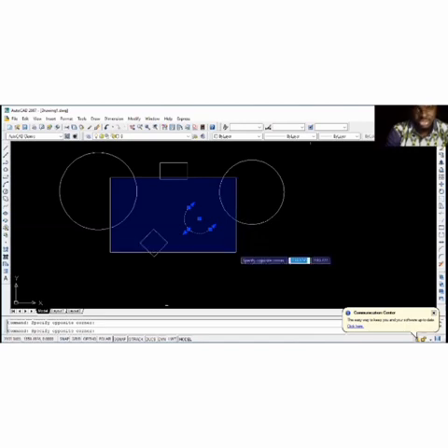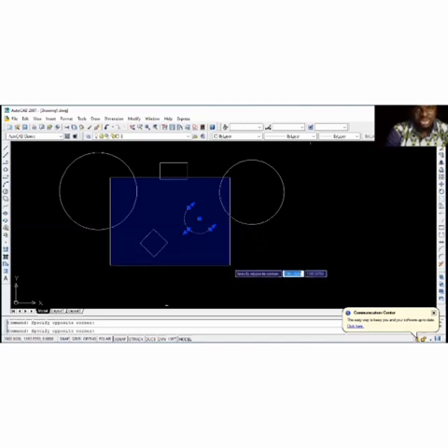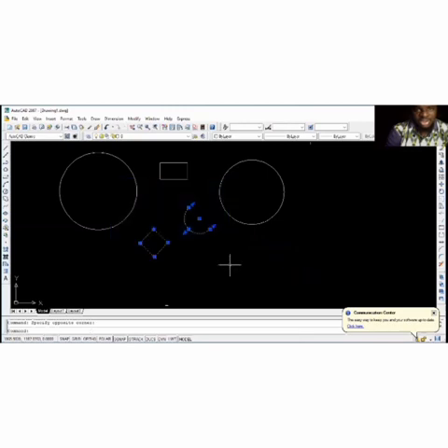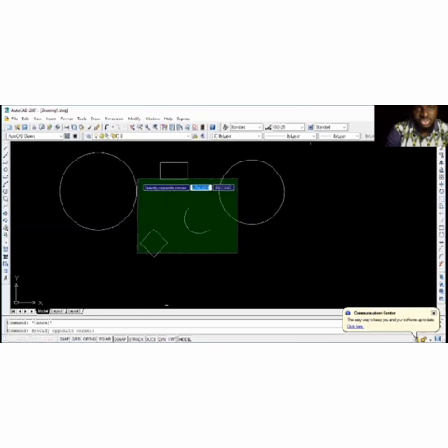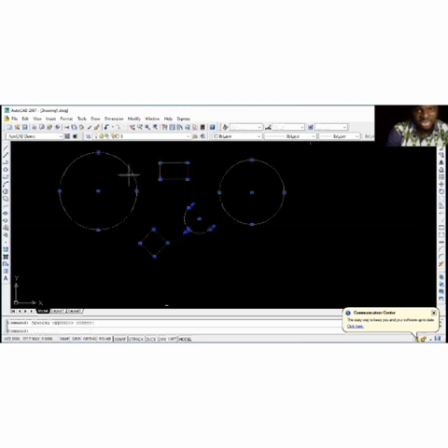So now, okay, for instance, now let me totally enclose this square under and then click on it. So you can see that it's just this and this because they were totally enclosed. But if it is the green color, once it just touches it, it is going to be what? Selected. So you can see that the green color is touching everything. Automatically, everything will be selected.